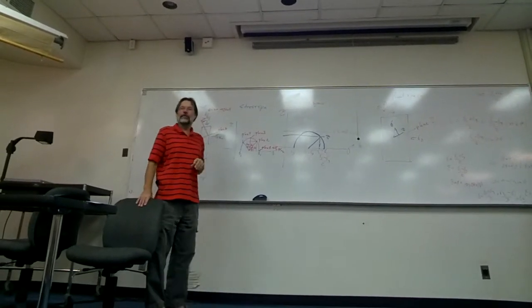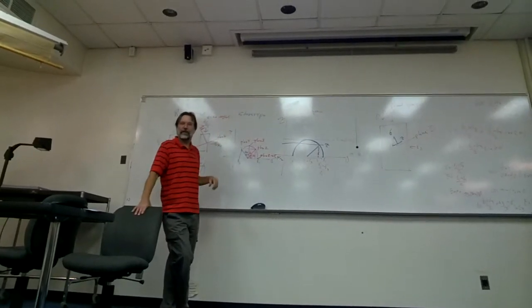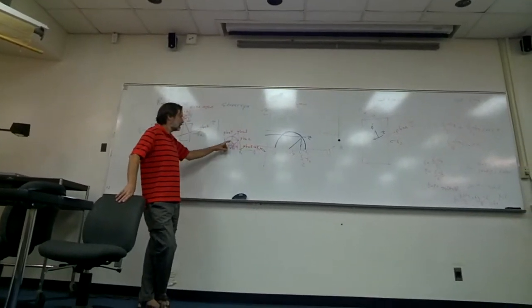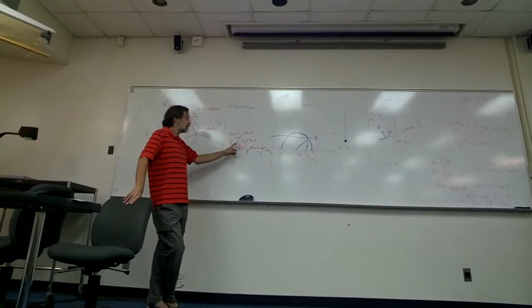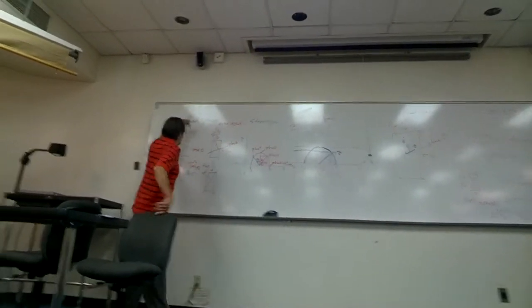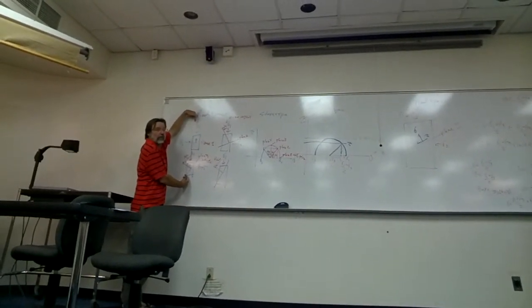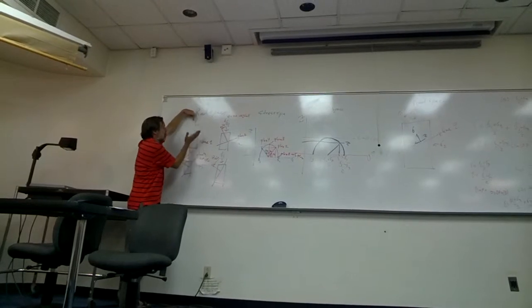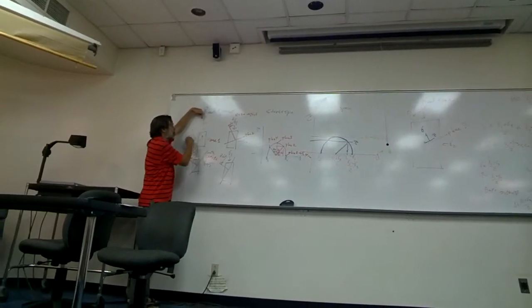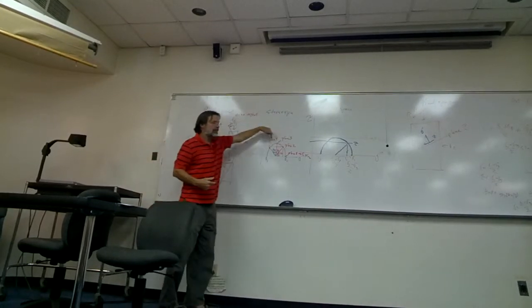This is an indirect proof of something that takes a long mathematical derivation: that the maximum shear stress is always 45 degrees from the long axis of the test specimen, or in the case of the principal stresses, a plane that's 45 degrees from sigma 1 and sigma 2. That's the top of the Mohr circle.